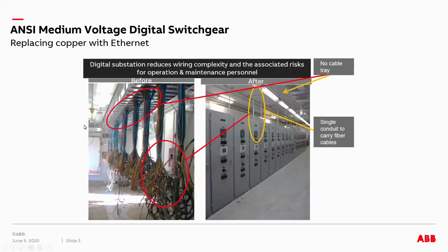So you have protection schemes, interlocking schemes, ATS schemes, and so on designed to work between the panels, between the relays of different panels. All those things have to be wired together. So there is a ton of wires drawn through different panels, and there's a dedicated cable tray, as I mentioned before.